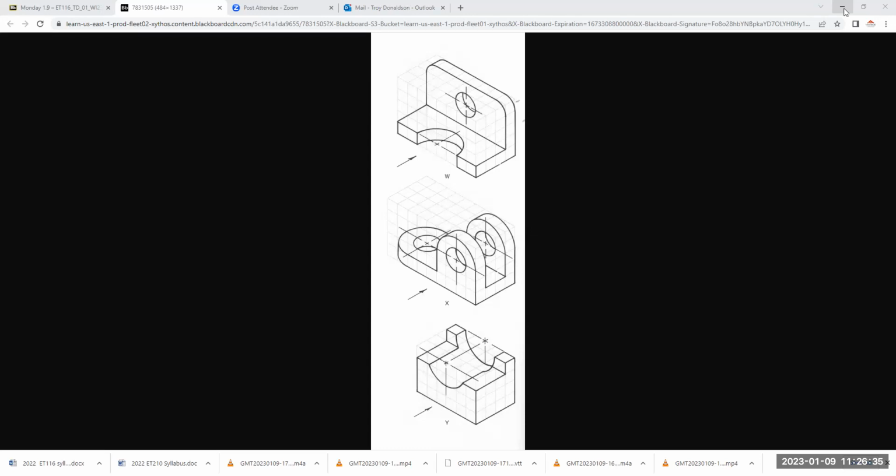All right, so now let's, I'm not going to draw the whole thing. You all can draw it. Get the hidden lines in too. So if you haven't worked with hidden lines in a while, remember that to use them, you got to load them. AutoCAD does not load line types. So here's the line types. And we are working with a continuous and a thin line. So if I pull it down and I wanted a different line type, there are none. And it's just doing that to save memory.